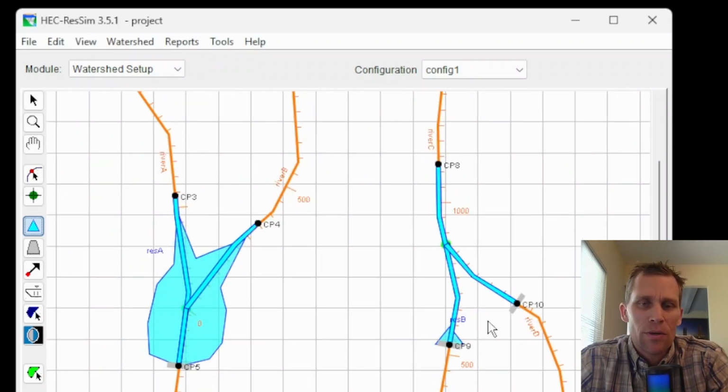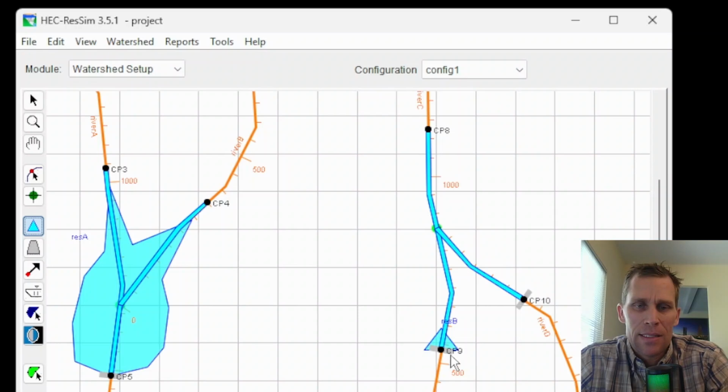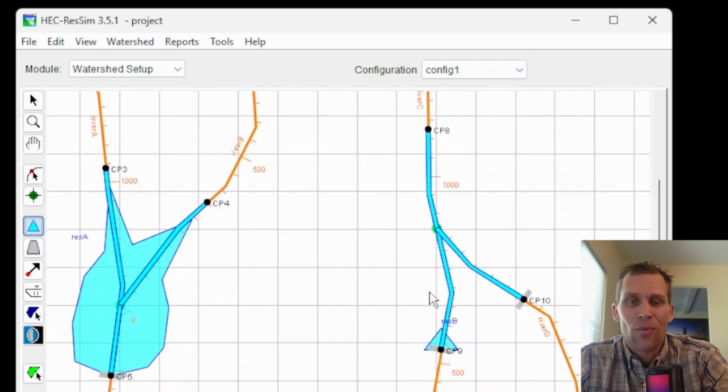And this looks a little bit wonky. So we still have the gray dam face line right here and right here. So it recognizes that they're both downstream. That's good. However, the little blue triangle just happens to be at one location. So again, this is a situation where we probably want to reshape this blue triangle.